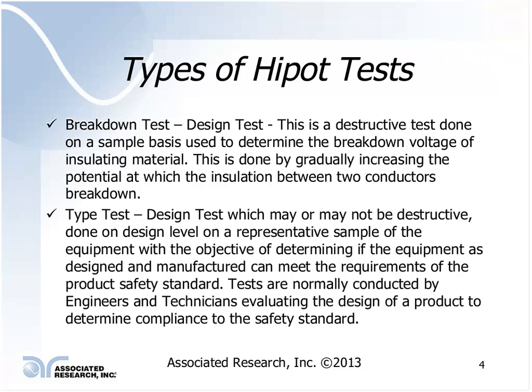They're checking for various problems or design issues that may occur with the product itself. When you're talking about a Hipot test, you're talking about creepage and clearance distances within the design of the product itself. And again, this is going to be based upon the application of the product.